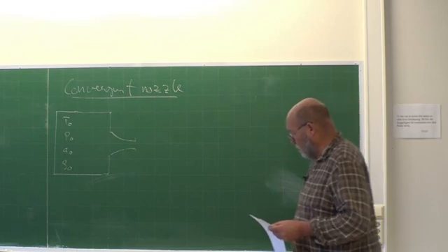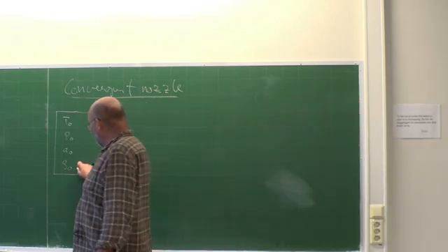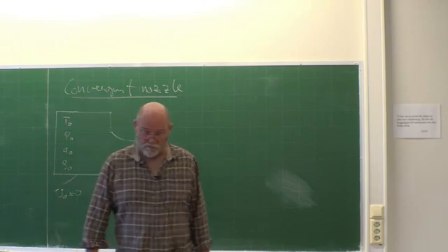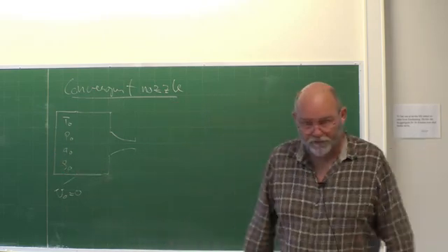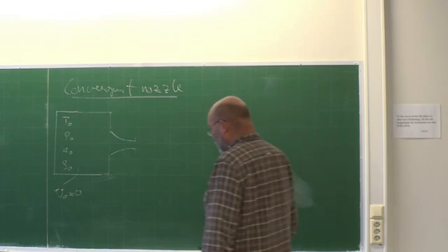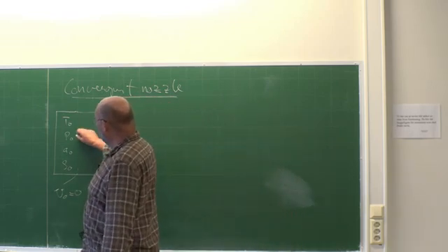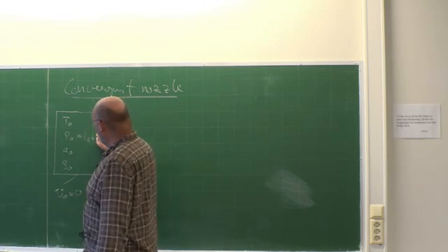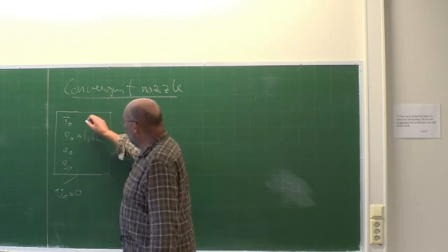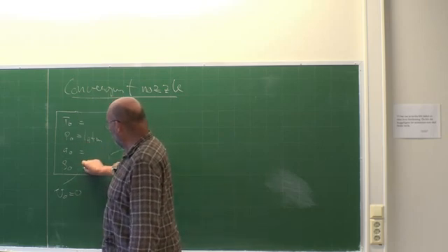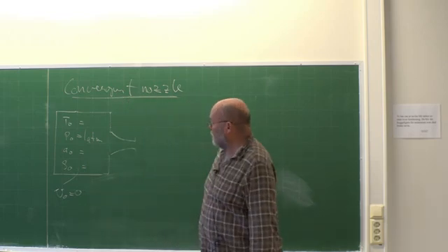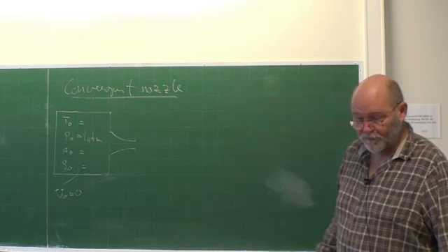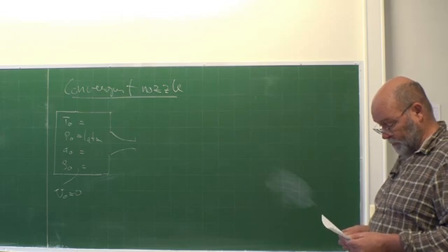And then also we have a velocity in here, which should be 0. That's an infinite reservoir, so we don't have any velocity here. So everything here should be standard things. You can put this one to 1 atmosphere if you like, and then put some numbers here. Speed of sound should be standard, 340 meters per second or something like that.